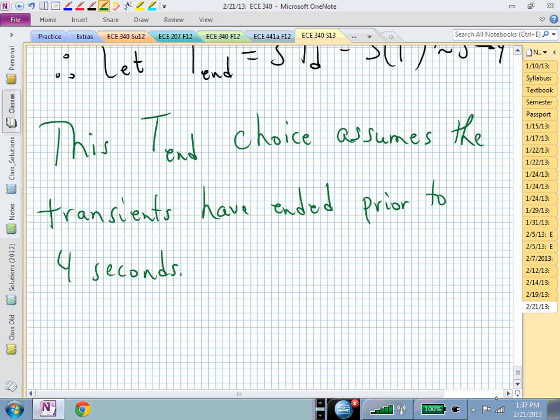If we kept our original natural behavior in our low-pass filter, e to the minus t in there, we found that that was 5 seconds, wasn't it? So it's going to take 5 seconds to reach a steady state, and we might want to look a little bit beyond. Maybe we want to look 4 seconds beyond our transient. So we might want to simulate this for 9 or 10 seconds if we hit that low-pass filter with a cosine of a frequency omega sub d of 6. Questions on that?